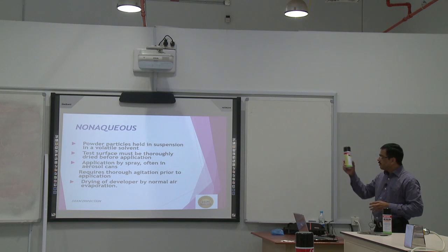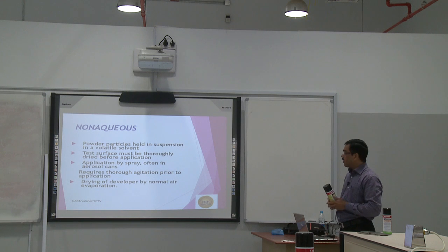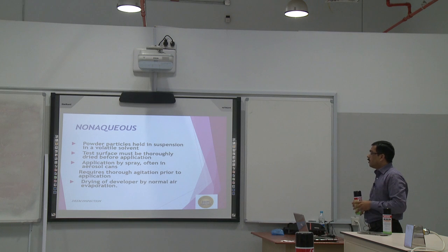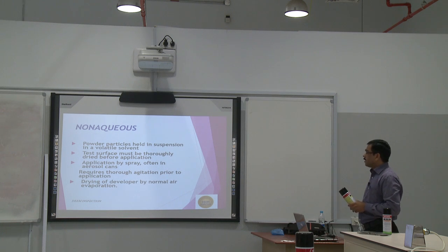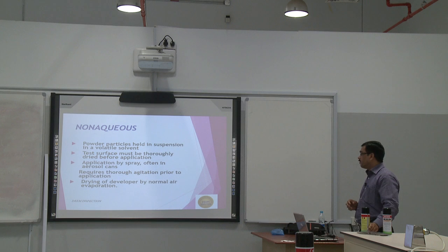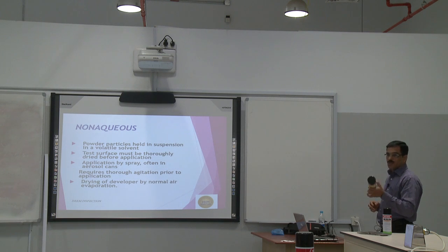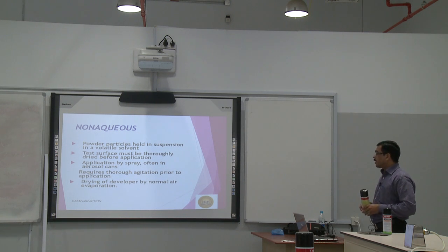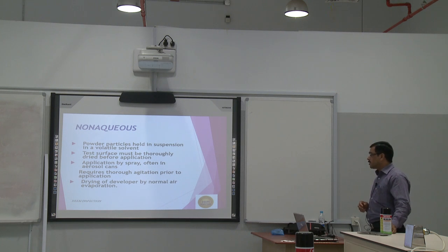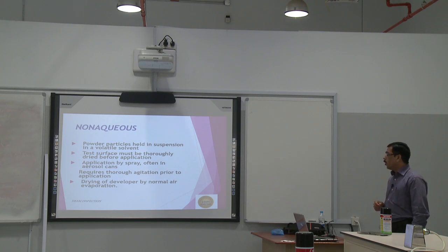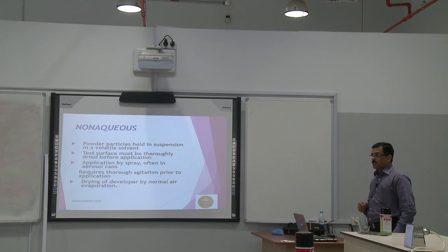These are the characteristics of the non-aqueous developer: the powder particles are held in suspension in a volatile solvent. The test surface must be thoroughly dried before application. Application is by spray, often in aerosol cans, like this aerosol can. It requires thorough agitation prior to application, and the developer dries by normal air evaporation.